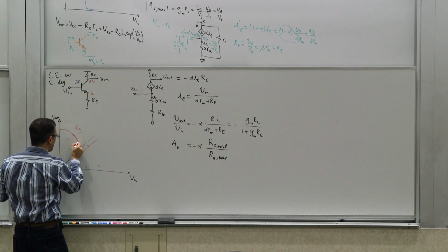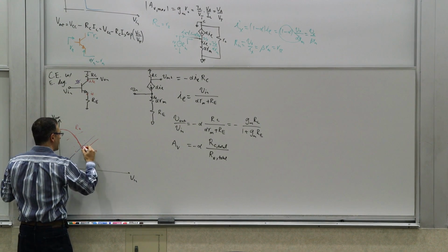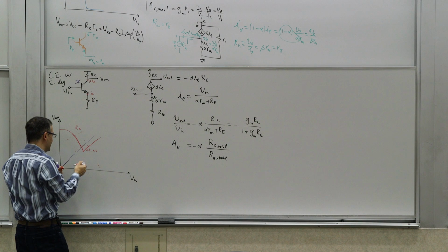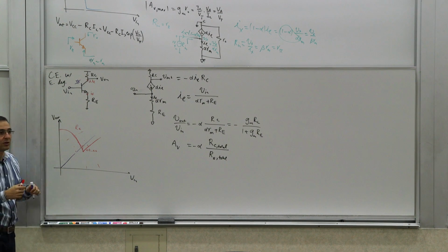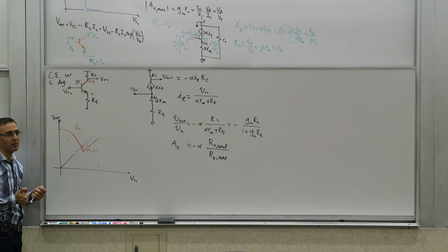Right? So this was going down as exponential. Once this voltage becomes like 0.5 or 0.6 volts, then this guy tracks it, because now the transistor is really not in forward active region anymore. It's in triode. I'm sorry, in saturation. So it just basically keeps going up.